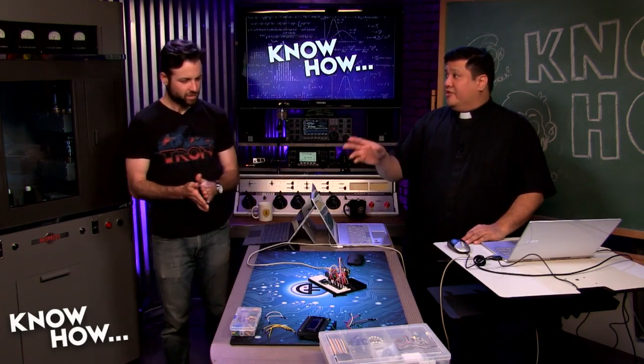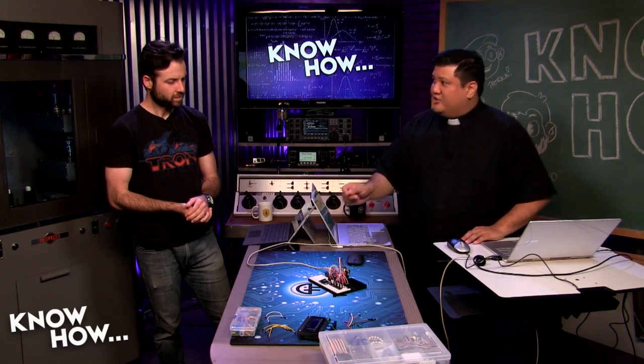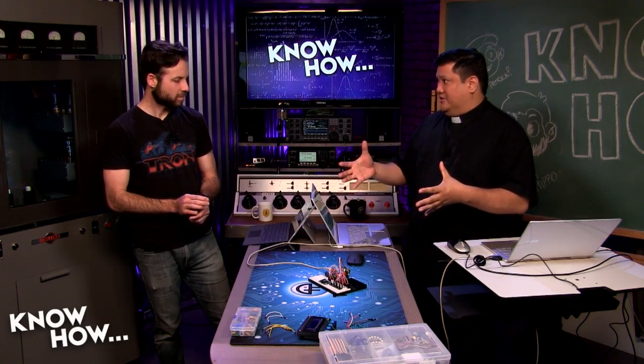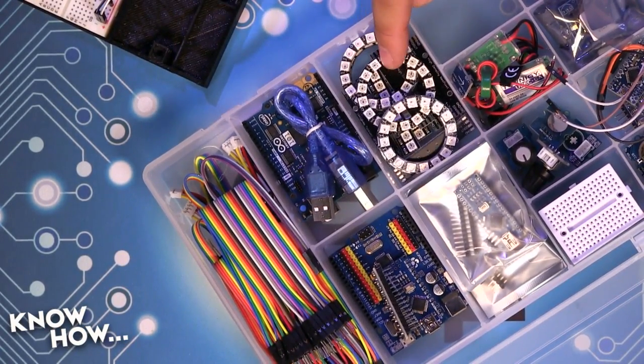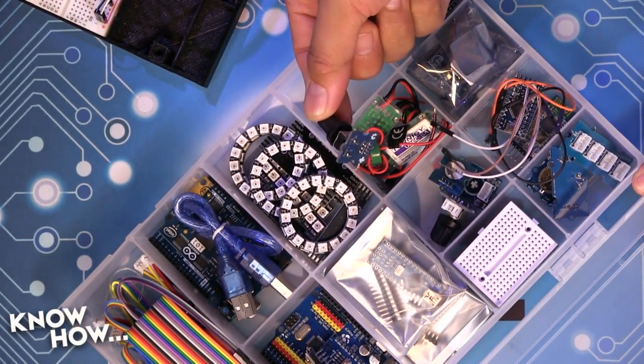All right. Very cool. So that's EEPROM. This is important because this is the first time that we've given them an easy way to do persistent memory. There is another thing, like for example, there are I2C devices that will take SD cards, and now you have a ton of memory that you can write to. Okay. All right. And we'll be playing with those. But now that we have I2C, it's going to be a lot easier to add these. In fact, if you look at my little toolkit right here, this is the thing I carry around with me anytime I want to be makery. So of course we've got our WS2812 rings, but all of these devices, these are all I2C.